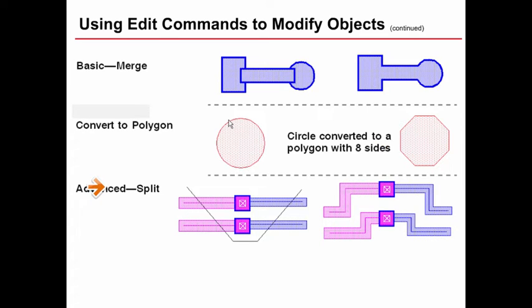Advanced split. Notice that on the left side of this split line is what we're going to have move. So when you split, you would start on this left side. That'd be the first, second, third, and fourth coordinate. And this is also at a 45-degree angle, because then that will hold these spacings where they are.